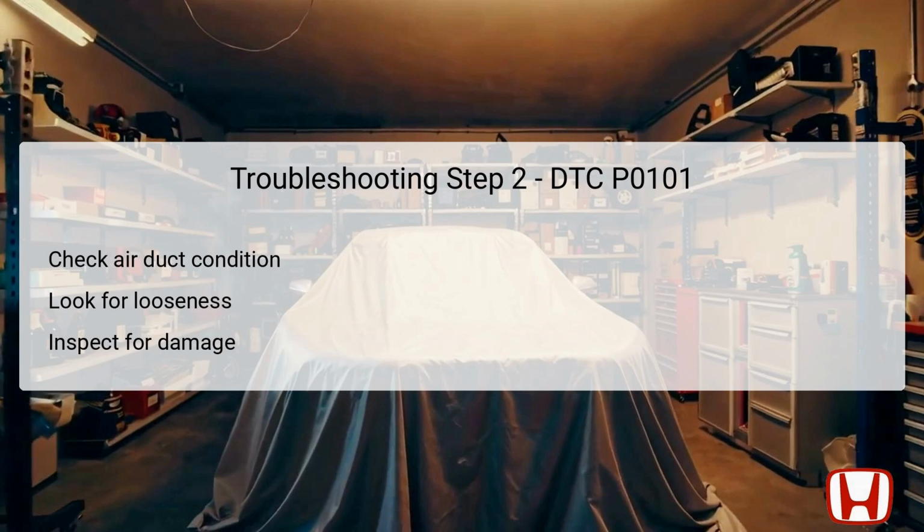If you discover issues with the air duct, such as disconnections or physical damage, these must be repaired or replaced. Once you have ensured that the air duct is secured in place and in good condition, you can then move forward to the next step of the troubleshooting process, which entails checking the air cleaner element.